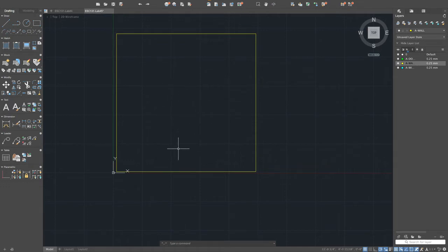As I mentioned, you can use 5 inches thickness for both exterior and interior walls to make our life easy. So you type offset, 5. First I'm going to draw all my walls.